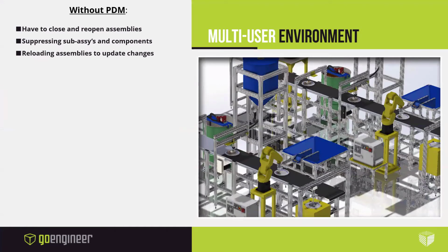Well, multi-user environments, this is another thing. There is a problem with working with multiple users on a network, but inside of SolidWorks it becomes a little bit difficult. From prior experience, I worked at one place where one of the coworkers would come in early. He would open one of the assemblies so he could grab everything, and then he would minimize that SolidWorks and start up a brand new SolidWorks. So he always had two SolidWorks running throughout the day. It was crazy. And anytime we ran into one of those parts, because he opened the assembly, he basically took read-write control of all the files inside of it.